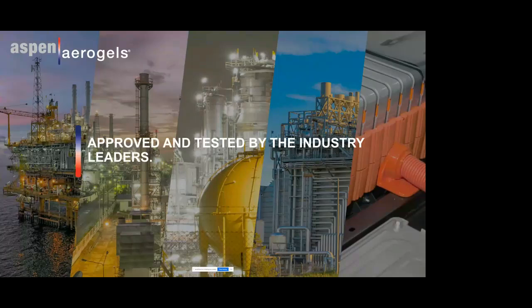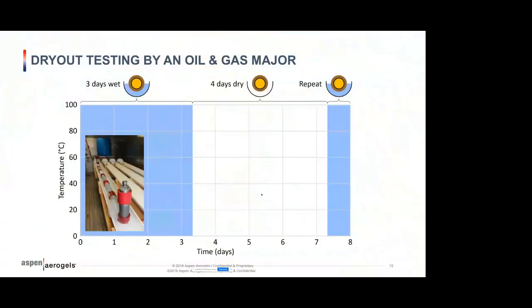So I'm going to talk to you about some of the testing that we've done in the industry. The first testing I'm going to talk about was done by Exxon, and this is a test where they were looking at the moisture uptake of the insulation. They tested two different types of insulation, Pyrogel against traditional mineral wool. They had these half pipes, which you can see with the red sections insulated with different products, and they filled the half pipe with water for 3 days, left it dry for 4 days, and repeated this process for 80 days whilst heating the pipe to an 80-degree cycle as well.